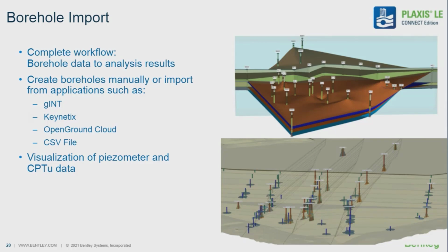So let's say you have a gINT project, or you have a connection with the Open Ground Cloud, you can update these boreholes and generate the surfaces in 3D. And also use the fence diagram to correlate the connection of certain boreholes in order to get the final 3D representation. We'll see an example about that today.